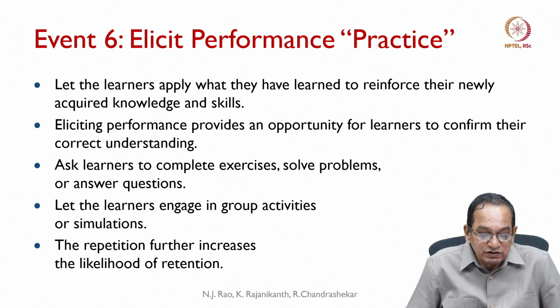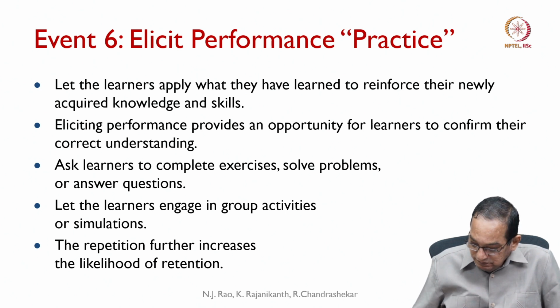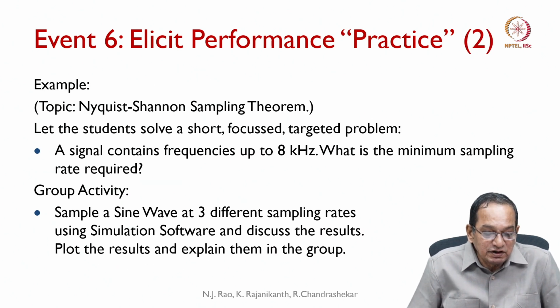Ask learners to complete exercises, solve problems, or answer questions. Let the learners engage in group activities or simulations. The repetition further increases the likelihood of retention. Example, again let us look at Nyquist-Shannon sampling theorem. Let the student solve a short, focused, targeted problem, a very simple problem, but the basics should become clear to the learner. A signal contains frequencies up to 8 kilohertz. What is the minimum sampling rate required?